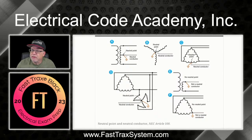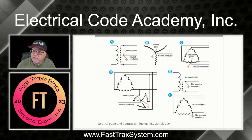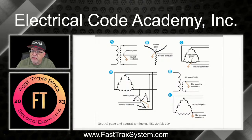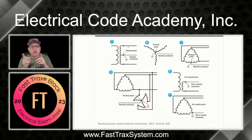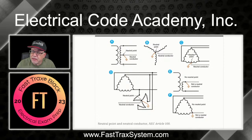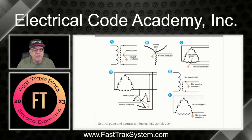So this first one here is an example of a single winding. This would be a 120/240 volt single phase, single winding where it's tapped at the midpoint. So from phase to phase on this winding is 240, but from phase to center tap is 120. This is the neutral point, and that is where the neutral conductor connects. That's why the informational note was important for the reference. From here to here, it's 120. From here to here, it's 120. From here to here, it would be 240. This is the neutral point between the windings, okay?